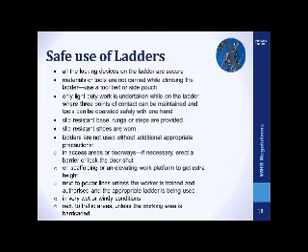Safe ladder use continued. Please ensure that all locking devices on the ladder are secure. Materials or tools are not carried while climbing the ladder. Use a tool belt or side pouch. Only light duty work is undertaken whilst on the ladder, where 3 points of contact can be maintained and tools can be operated safely with one hand.